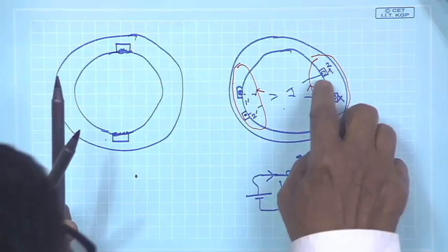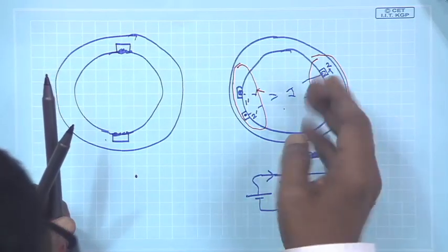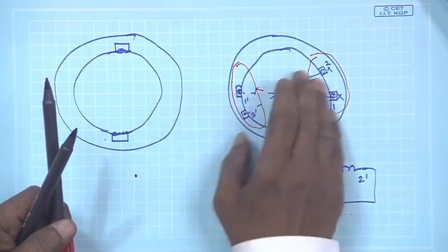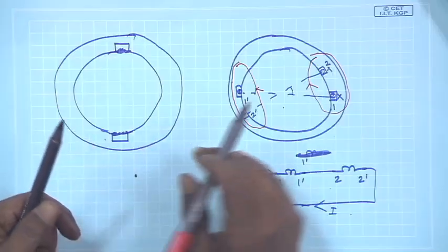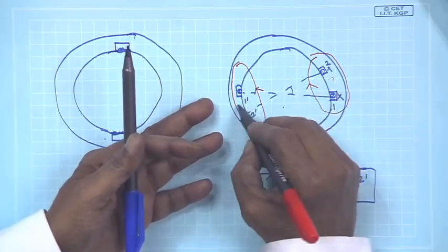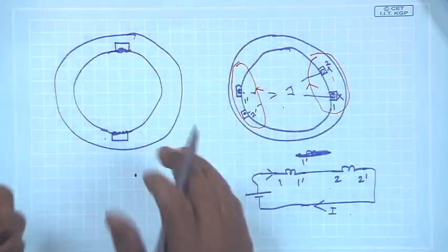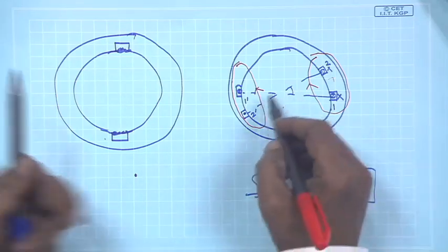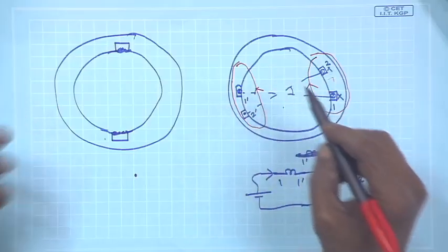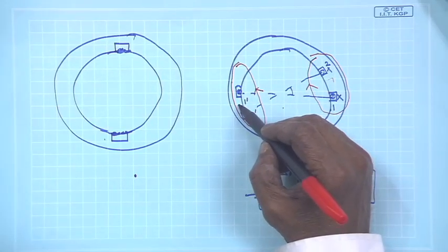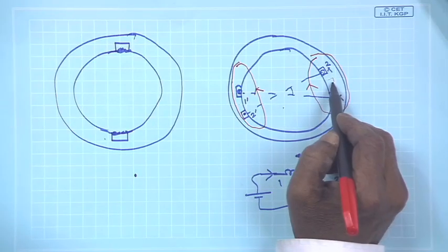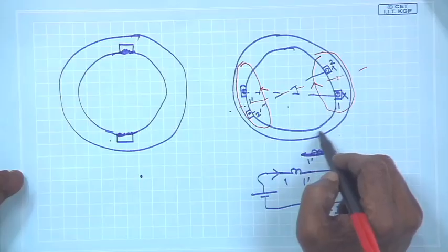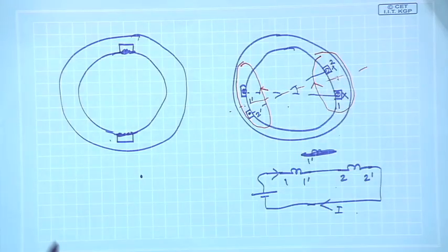Therefore, any band of cross current distributed over space, and opposite-side dot currents equally distributed, is in effect as if a single coil in the middle producing a field. So each one produces two poles, and the resultant will be like this. This half will become the south pole, and this half will become the north pole.